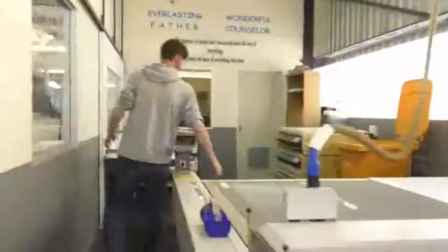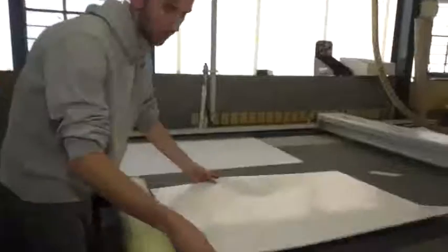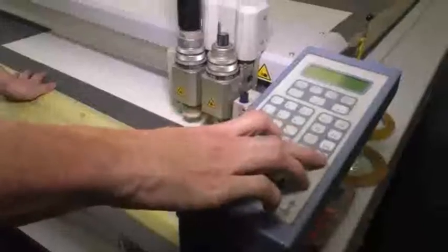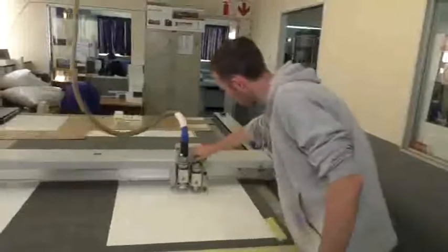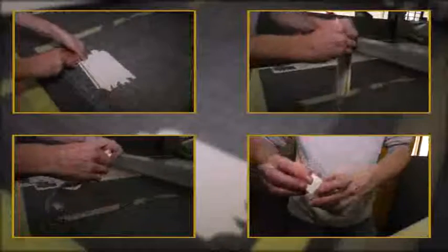Once they are happy that the die traces meet all the required dimensions and functionality specifications, they use a digital cutting and creasing machine to create a sample carton. Part of their job is loading and setting up this machine and making necessary adjustments during operation to ensure a perfectly cut and creased sample. Once cut, they manually glue and assemble sample cartons for customer approval. In the process, they check to make sure that all overlaps and locks function as designed and that the intended product fits within the carton dimensions.